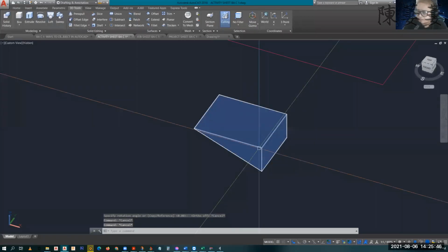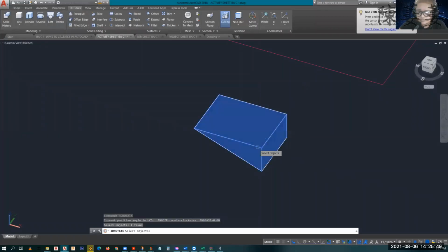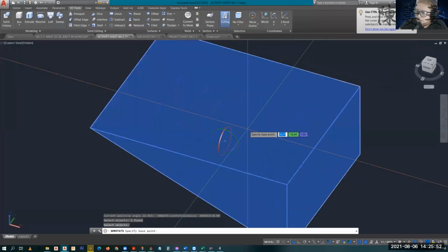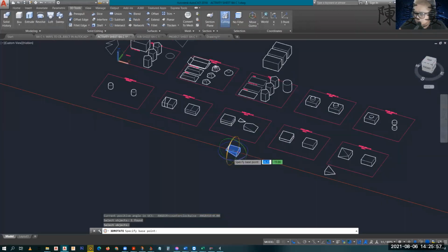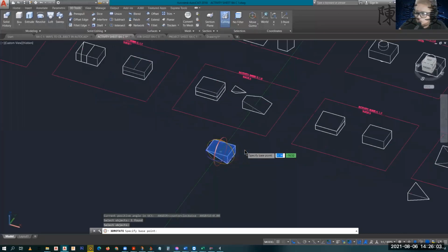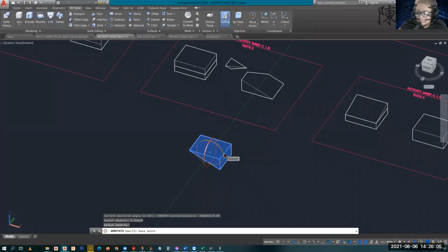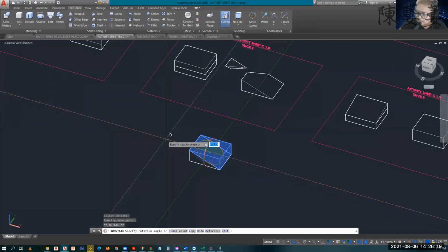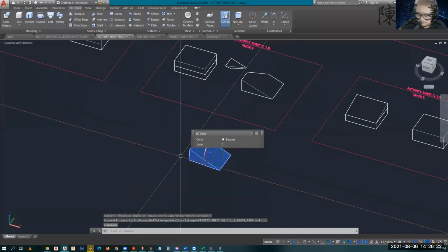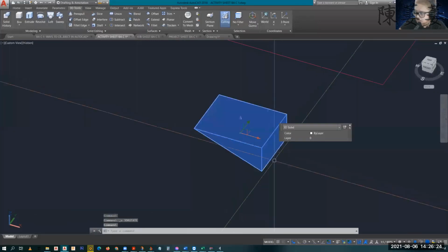So 3D rotate. So here, after selecting the object, you will see 3 axes here, the red, green, at saka yung blue. So you need to select yung axis na iikutan niya. For this one, we need the green one. So i-click ko yung green. Yan. So iikot na siyang paganyan. Hindi siya perfect na ikot.